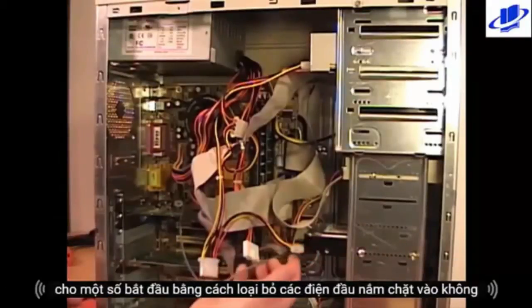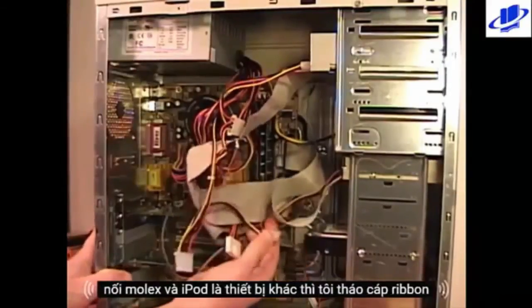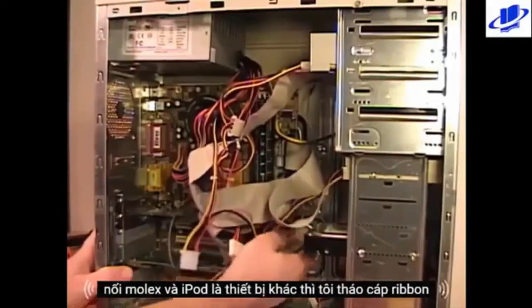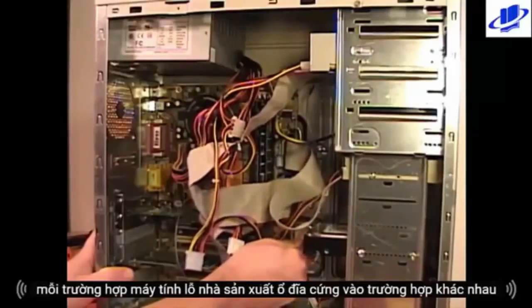First I'll begin by removing the power lead, gripped onto the Molex connector, and then I pull it out of the device. Then I remove the ribbon cable. I grab the ribbon cable close to the connector and then pull straight out from the device.